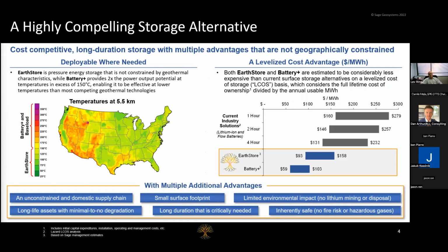then it is actually cost competitive with all other potential energy storage, because really there is nothing available today as storage in the space between 4 hours and maybe a day or a few days, except hydro pump storage. Well, hydro pump storage, you're not going to build at 3 megawatt capacity. It's usually hundreds of megawatts. And also you really need to be in a mountain area, because otherwise you will not be able to build it.